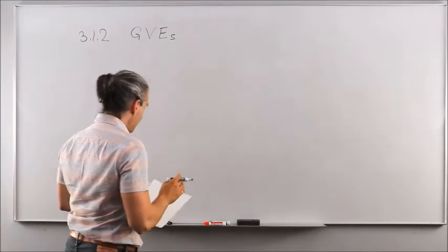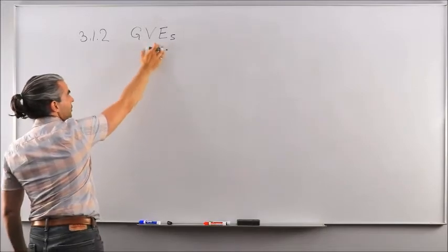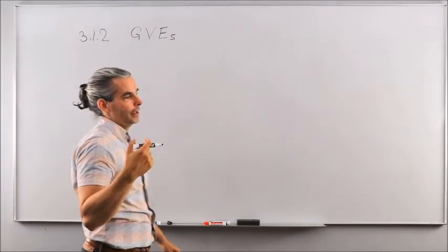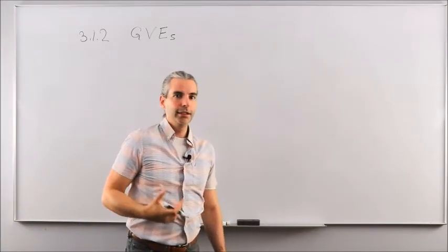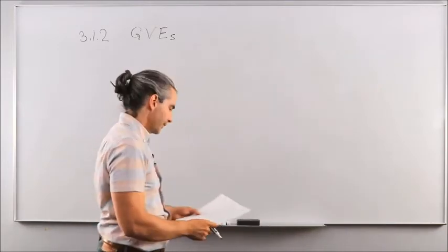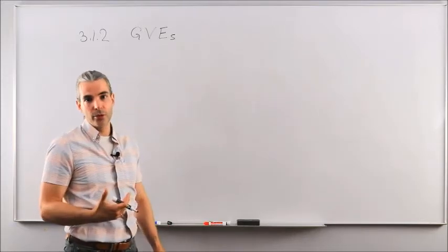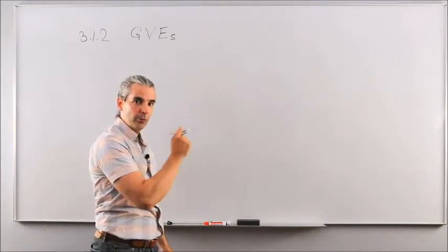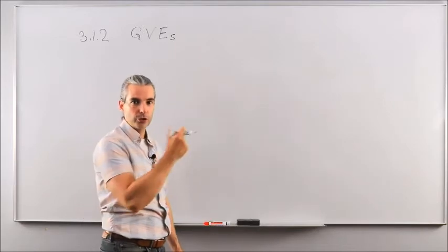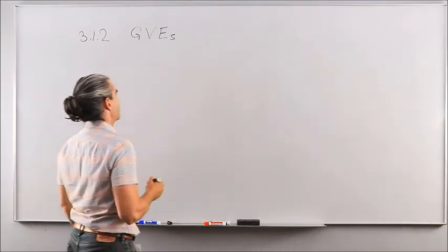Okay, so the starting point to derive the Gauss Variational equations are the da/dt, de/dt, di/dt, d(RAAN)/dt, d(omega)/dt, as functions of f_r, f_theta, and f_z, which are the x, y, z components of the extra term we added to the two-body equation, the perturbing acceleration term, as seen in the orbital reference frame.